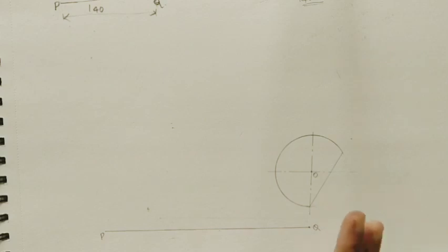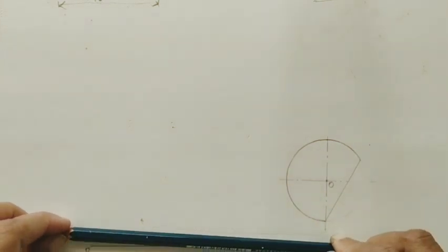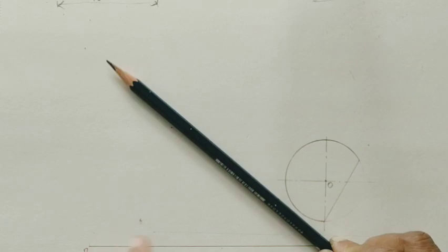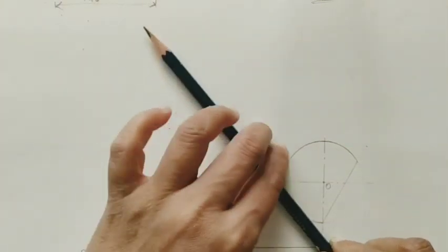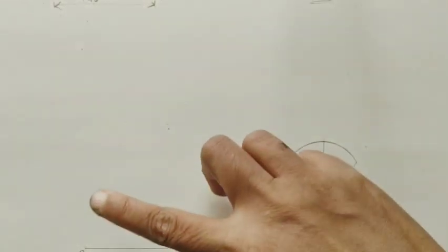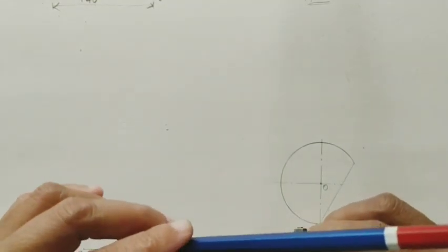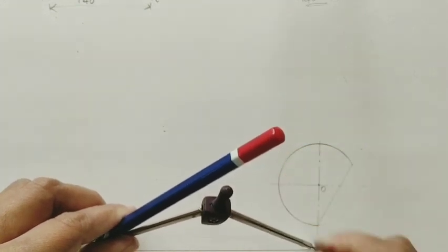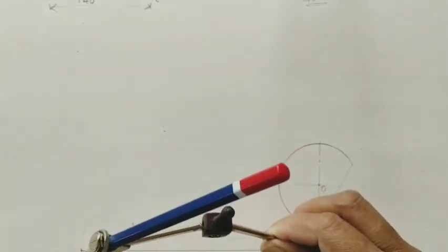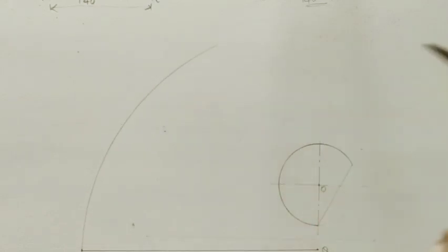Now for this we need to do the involute. For doing the involute, taking whatever length is there, the same length, I am tilting like this. Whatever radius is there, whatever PQ length is there, the same length will be coming here like this. Let us do it using the compass, do an arc here of the same length. Q as center, do an arc here. Because Q is the fixed point here, take Q as center, PQ is the radius. Do an arc of some length like this, up to some length.